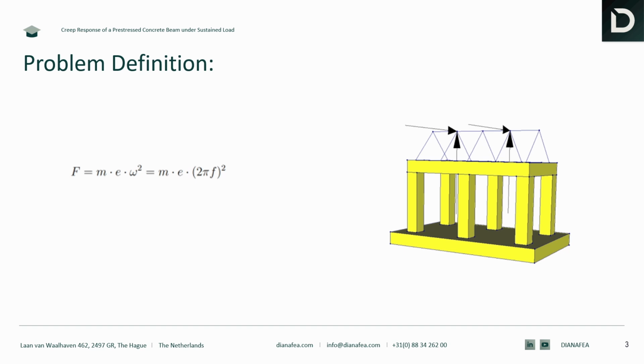two heavy duty compressors, one high pressure unit with a 60,000 kilogram weight and a low pressure compressor with a 40,000 kilogram weight. Both of these compressors spin really fast. We are talking about 6,000 rounds per minute, which is 100 rotations per second. That kind of speed creates dynamic forces due to the imbalance in the machines.